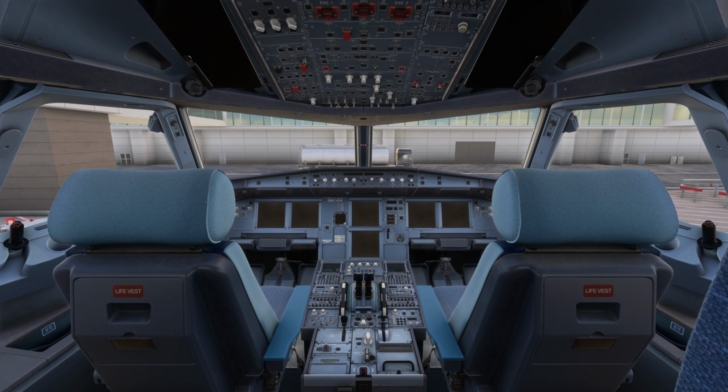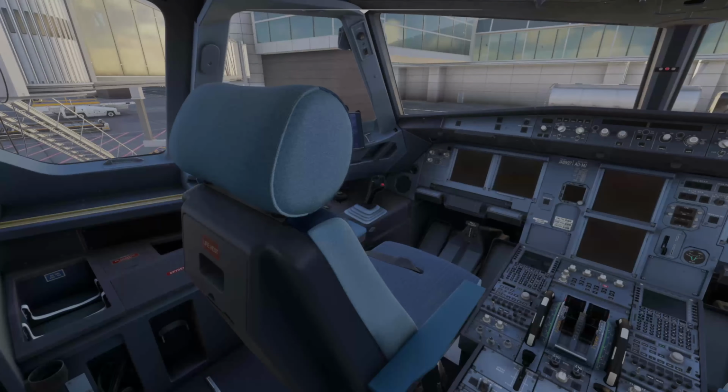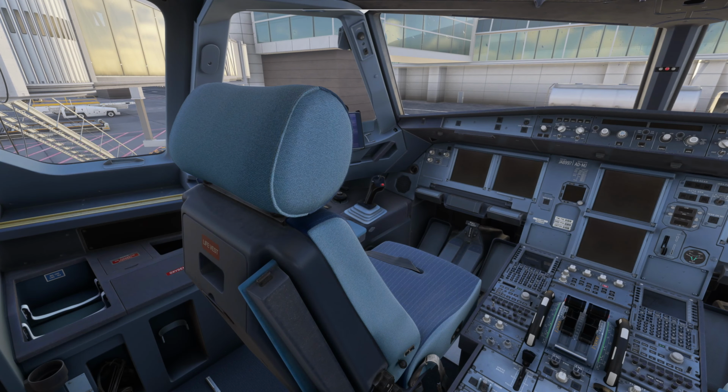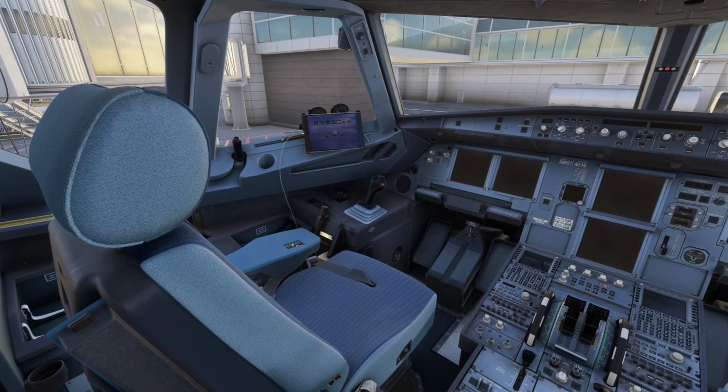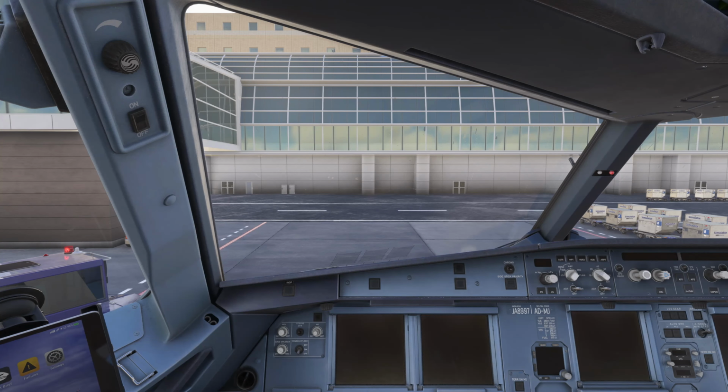It's also important to mention that any flight crew must review all the OEBs, or Operations Engineering Bulletins, applicable to that aircraft, with particular attention being paid to the red OEBs. Okay, so as we make our way into the captain's chair in this cold and dark aircraft, there are particular flows that we need to follow for the preliminary cockpit preparation.